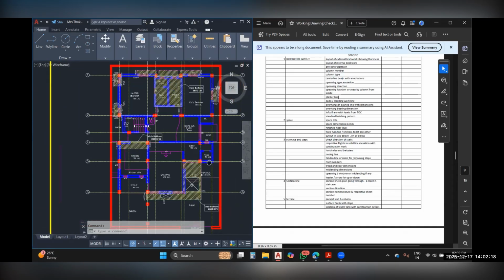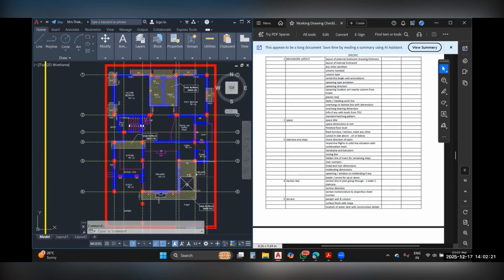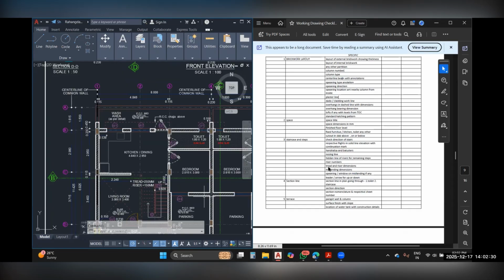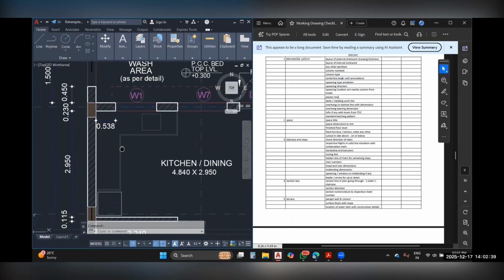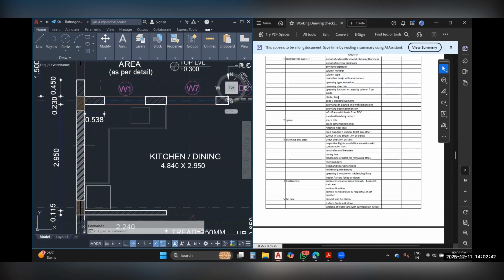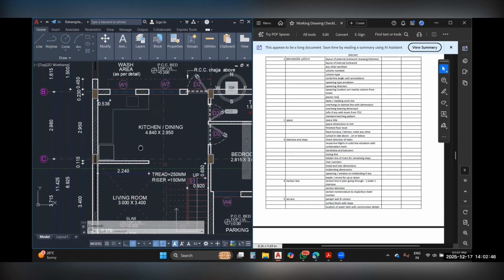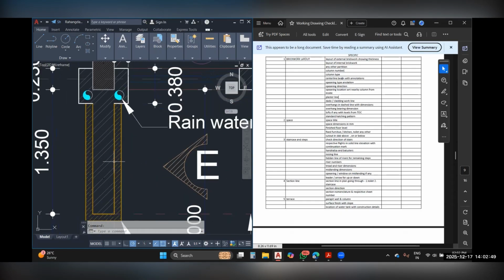This is a separate drawing made for constructing specific elements, overhangs, lofts at lintel level. Standard hatching patterns represent various materials. For example, this hatched line at an angle is representing brickwork, whereas a dash-dot line is representing stone. You can add several such hatching patterns in order to specify the materials for the building.